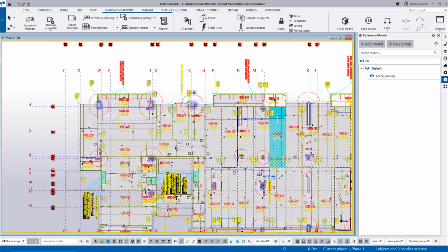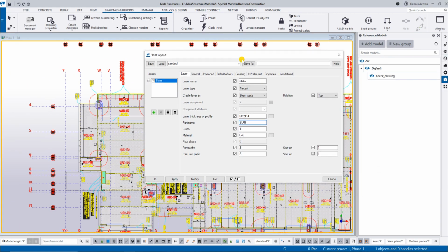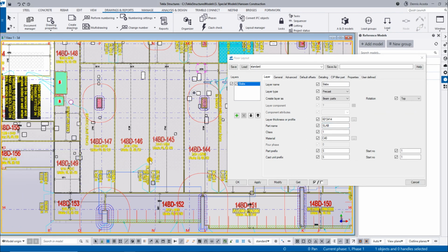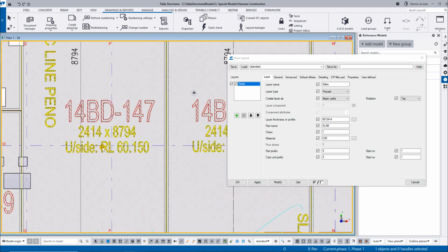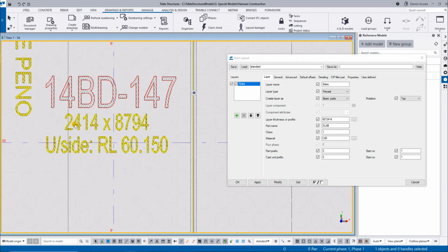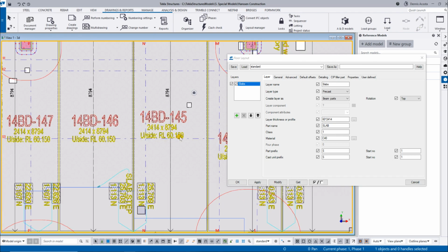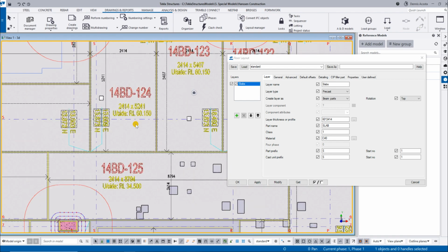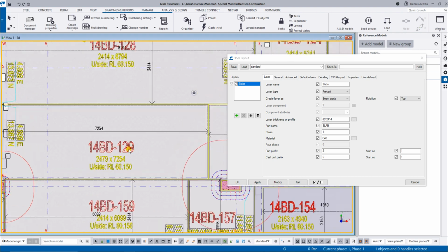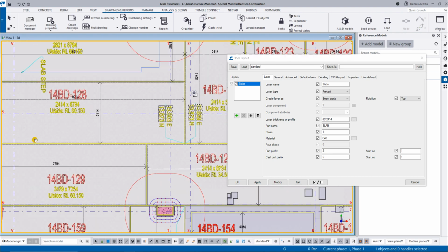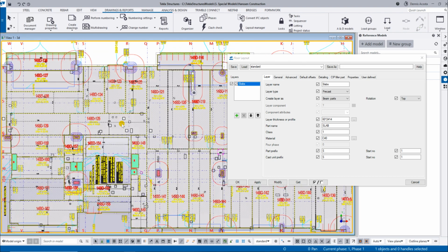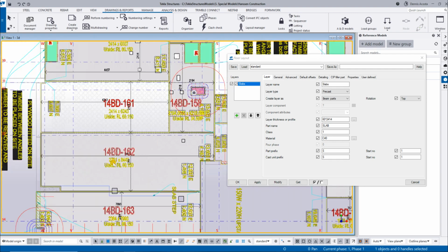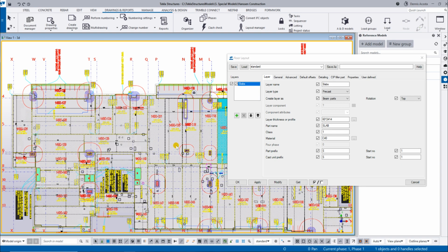So from here, I can now use my floor tool. As you can see here, I can look for all the similar widths of the slab. Let's say this one is 2414, 2414, 2414. So I will do the 2414 first, and then for the other ones, I can model them separately, because some slabs here are different sizes.